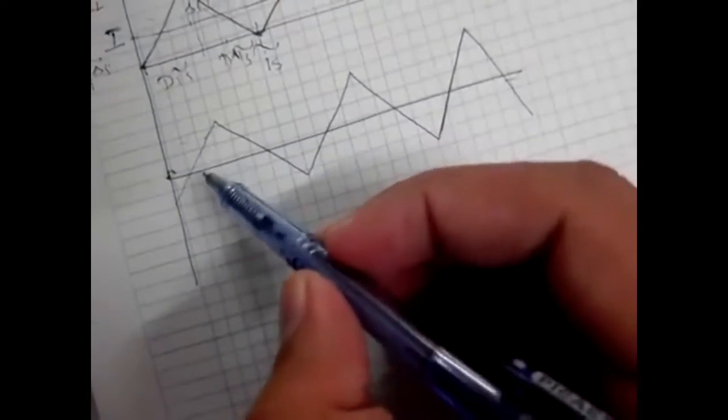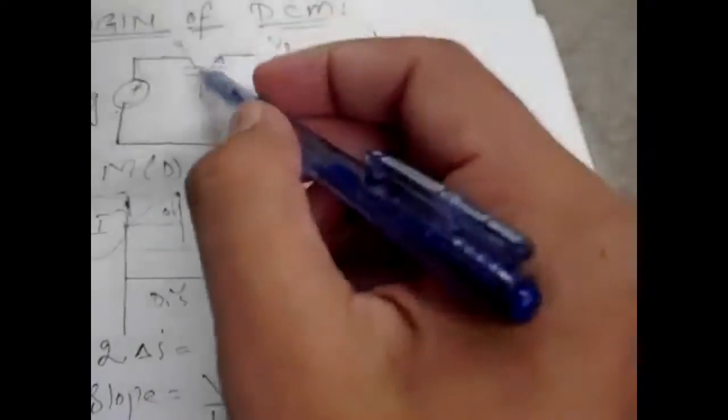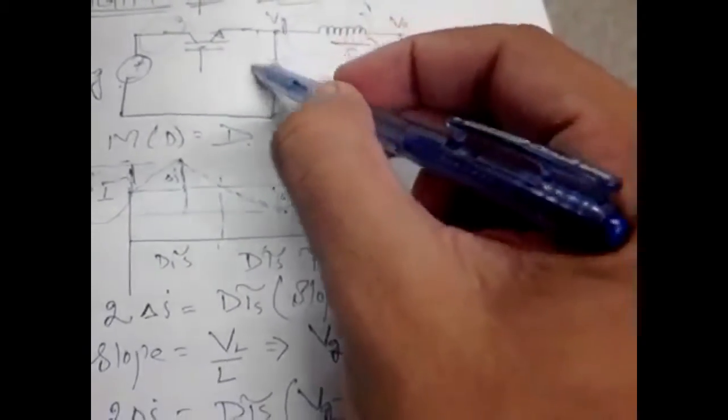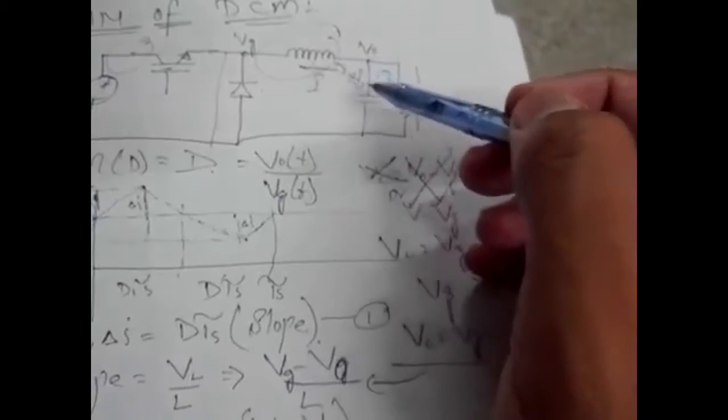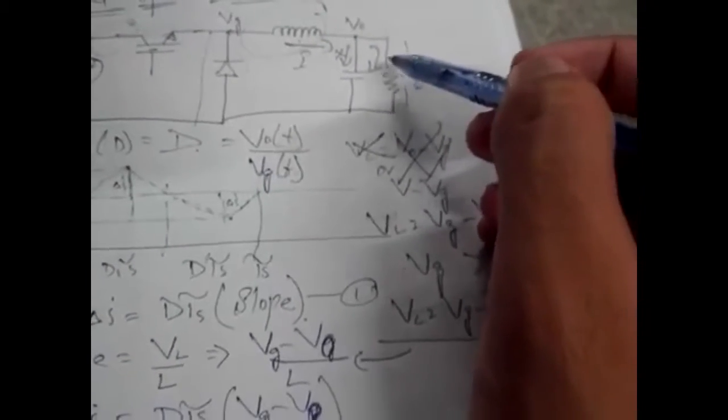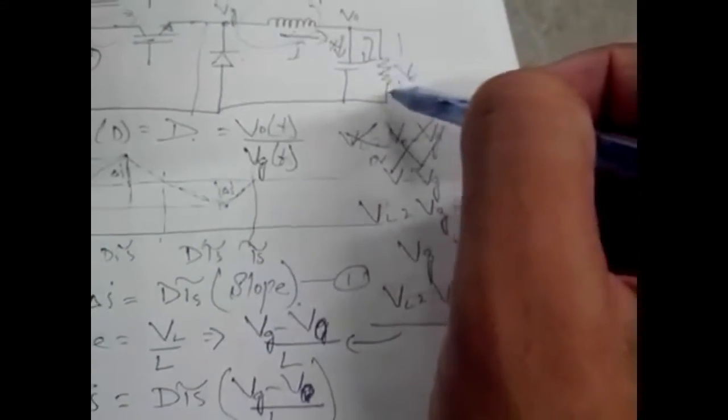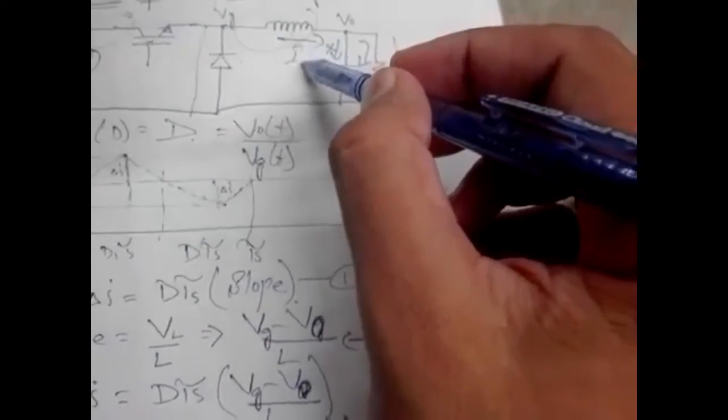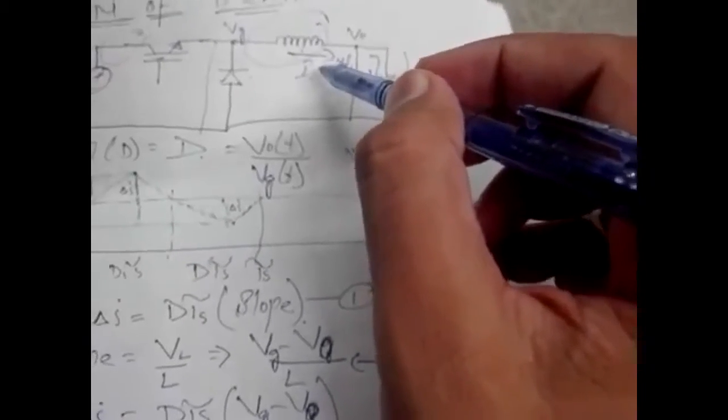So as we see here, the inductor becomes energized. Now when we switch off this and switch on this switch, what happens? This portion becomes separated, and the inductor provides the current to the load, but the load is very high, so very small current flows in this inductor, because the load resistor is very high, so this inductor current becomes de-energized in a very short time.